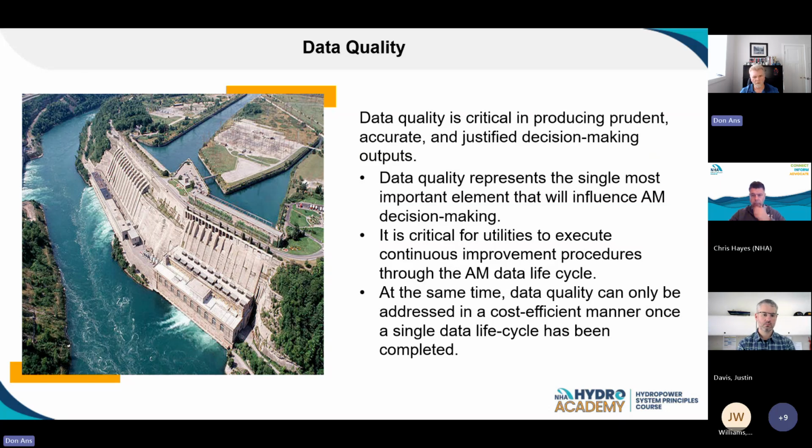Also, I mentioned earlier about the management of change. So keeping up with asset data and the changes in asset data, also very important. So again, processes to ensure that, if a transformer is replaced or a breaker is replaced, that new asset data gets put in, and the appropriate maintenance tasks are put in, et cetera, et cetera. So really, really important to manage that asset data quality.